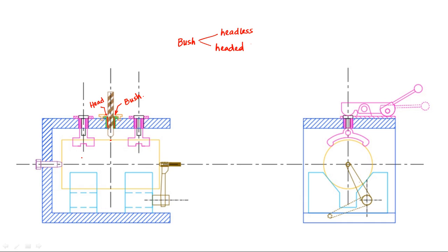Now there is another advantage of using a bush. Suppose you need to make a hole, and the diameter of that hole is smaller than the diameter of the existing bush. In that case, we can use another bush which has the same dimension as the hole, and if we use that bush, then we can easily make the hole on the surface with the help of another drill bit which has the same dimension as the hole. Okay, so that is the advantage of using a bush.